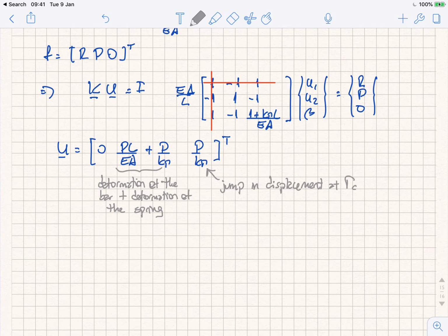Excuse me, 1 second. And we got to the solution of this problem very simply because we considered the same material properties at each side of the bar, right? So that means that there is really no jump in the strain here. And this is very important because if you just change the material properties at either side, so if I have, for example, EA on the left not equal to EA on the right, we are unable to get two independent kinematic fields with this formulation, right? So we noticed this when we submitted the paper, and then basically the solution to that was to just use the standard IGFEM formulation, which has that term with the alpha enriched degree of freedom, that is reproducing that jump in the gradient, and then we added the strong term into it, right?